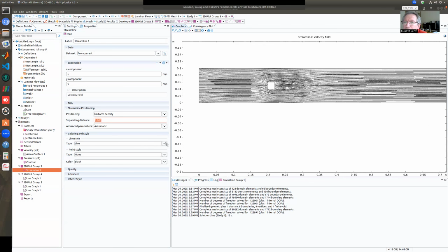Hala laminar flow değil mi? Yeah, it is laminar flow. I mean, something circulating and rotating doesn't mean turbulent flow. At the very beginning, when we started the console and set up the project, we selected laminar flow and we cannot do any turbulence here. So we have to select turbulent flow at the beginning to do turbulent flow simulations.